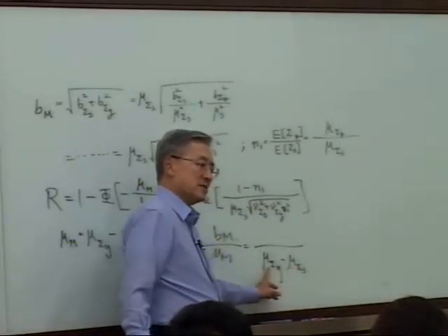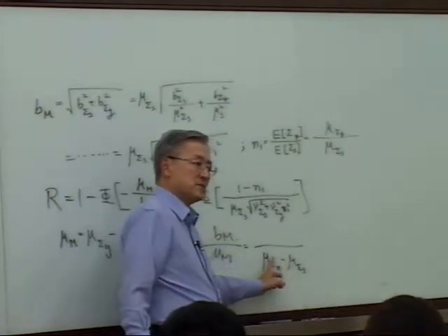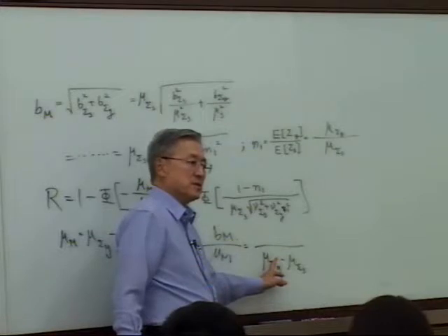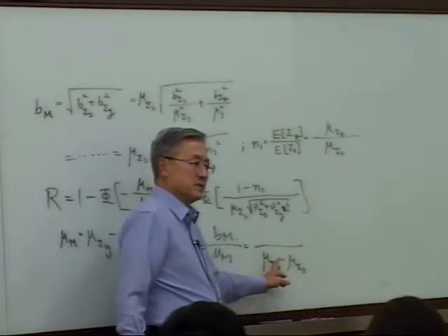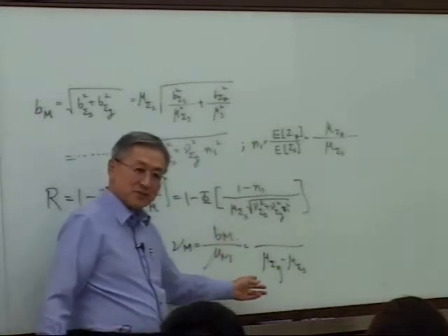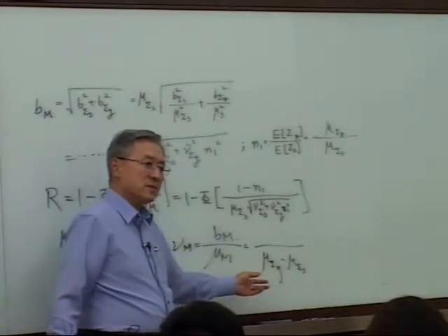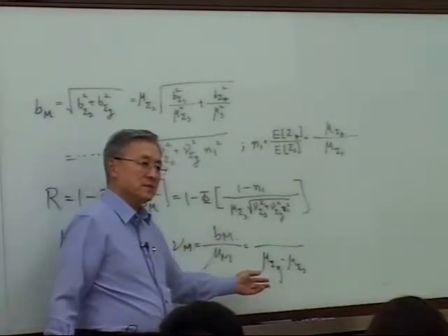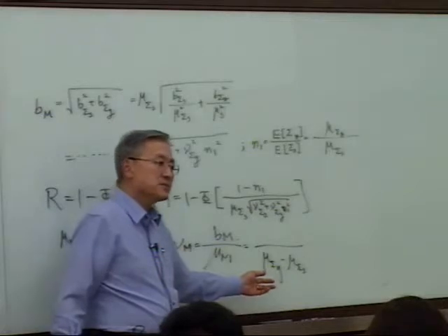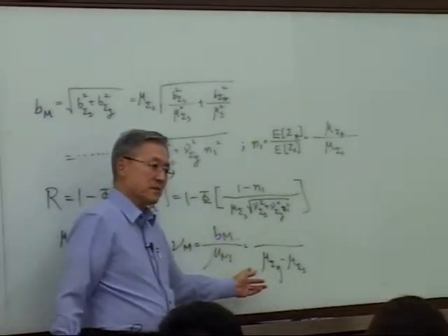The yield has to be equal to the actual stress. Then this is equal to 0, which means there is no safety margin. No safety margin, what does that mean? What's the reliability level? It's about 0. So it's not going to work.